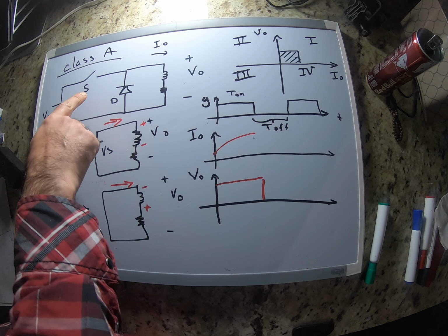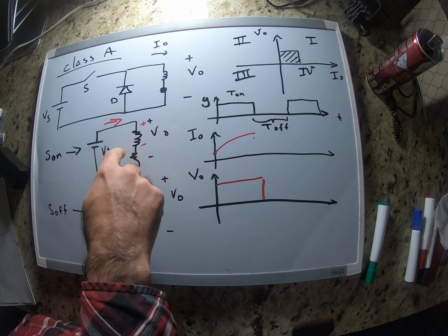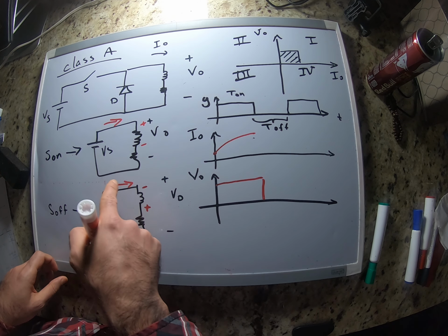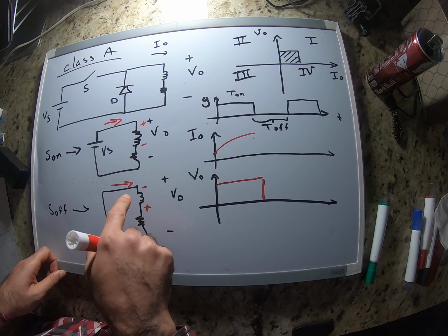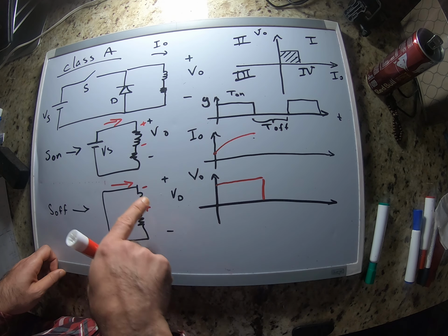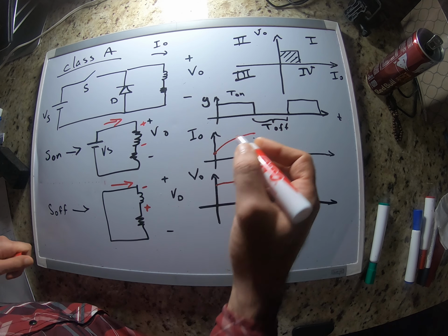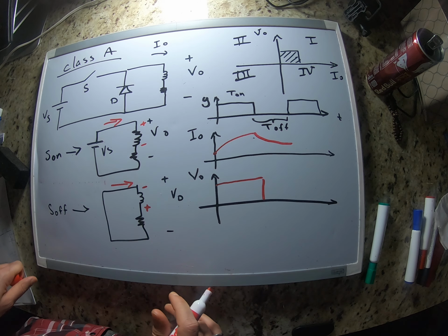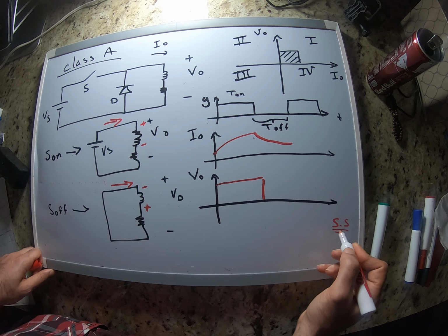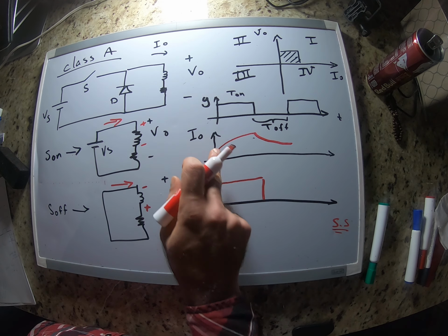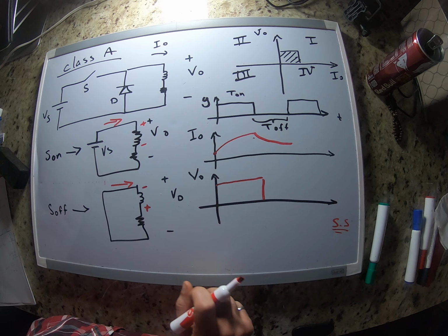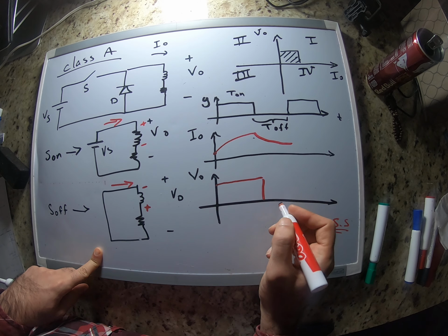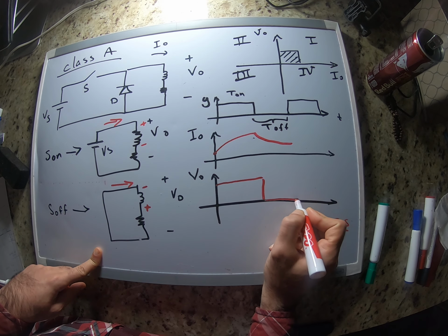Once the switch is open, then we have this circuit, right? So in this case, the energy stored in the inductor starts releasing into the circuit, into the resistor. So at this point, the current is gonna drop down exponentially. And again, we assume that we are in the steady state mode, right? So the current is gonna reach, let's assume, its initial point, right? And the voltage is gonna be 0. And this keeps going on.